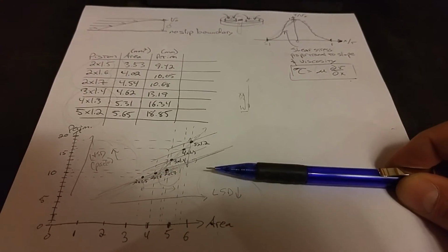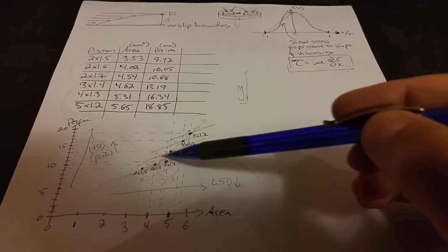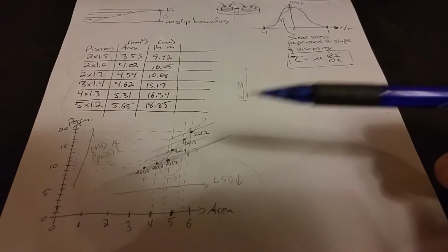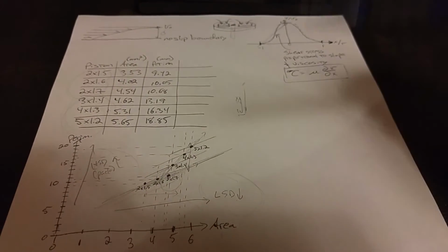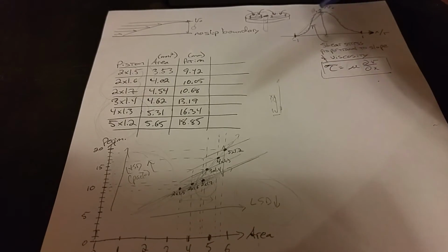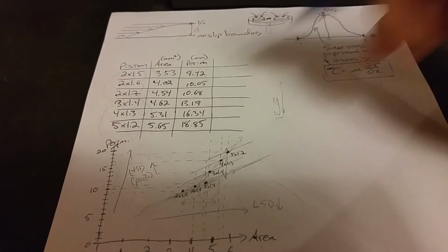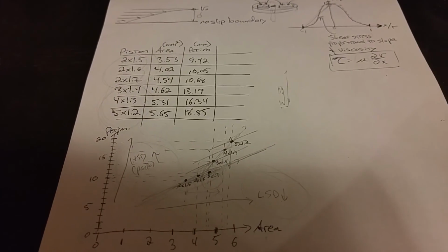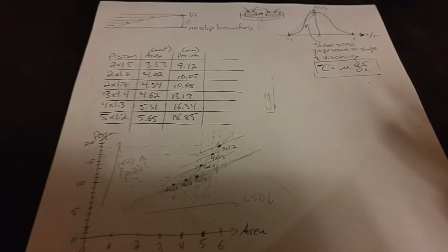Now the price you pay for using a piston like this is that you tend to suffer in jumping performance. So if you're on a bumpy outdoor track that has very large jumps, then you're in trouble, right? Because you need to compromise either the setup or your driving style. I might use a 2-hole with a large piston size to give me relatively low pack, but I will end up suffering in the jumping performance. So when the car lands, it's going to bottom out.